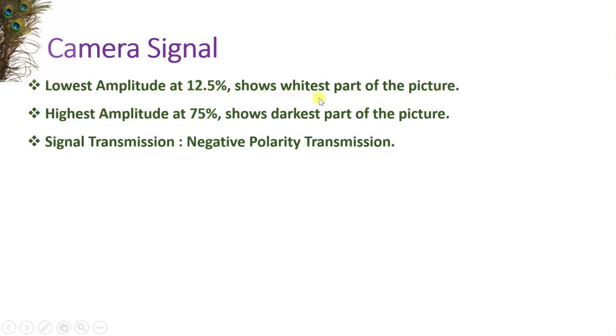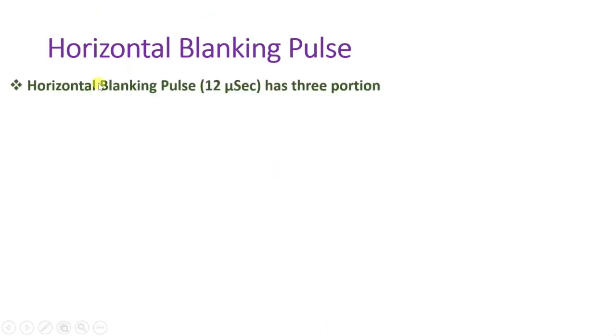Time H is 1/15,750th of a second, which equals 63.5 microseconds. In the image below the signal, the black edges show blanking. H blanking moves into the image to show the effect on the screen.